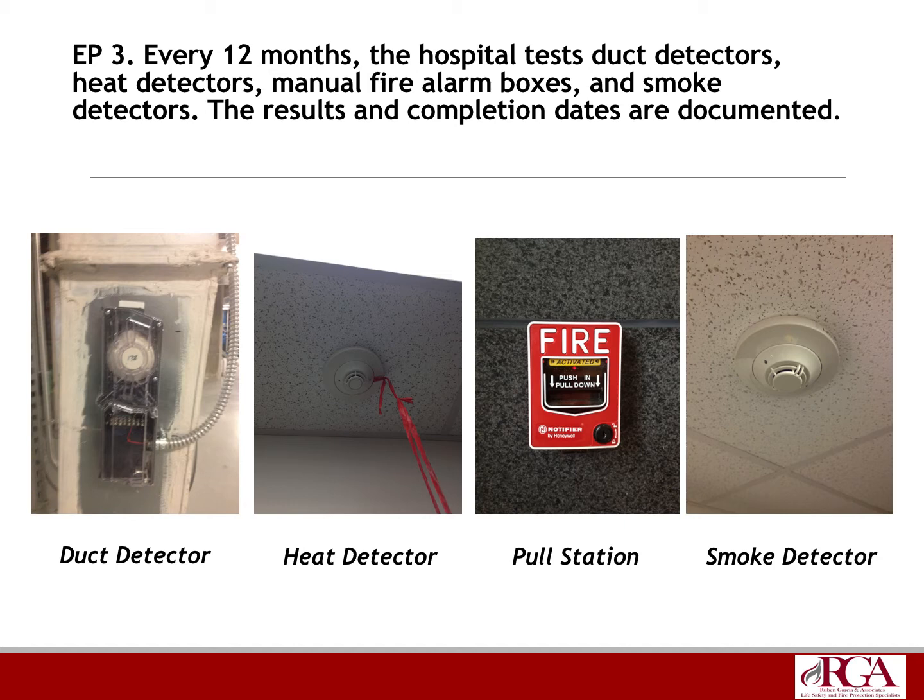And then you have your smoke detector. Your smoke detector is your early warning device. Smoke detectors are very important because they tell you when the fire is in its incipient stage. That is, when it's just fresh and beginning. So it's going to give you time to evacuate, and it's going to notify folks when the fire alarm system goes off. Conversely, a heat detector only activates when the flame or heat has reached a predetermined temperature. So a heat detector versus a smoke detector is day and night, where a smoke detector is going to let you know as it detects smoke. A heat detector is going to let you know when the fire's kind of gone out of hand already. I mean, it's a full-blown flame to activate that heat source, or that temperature rather.